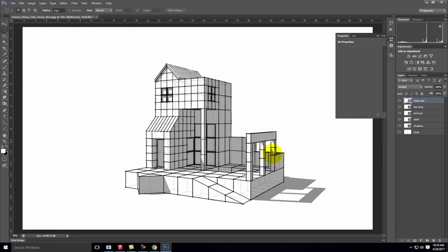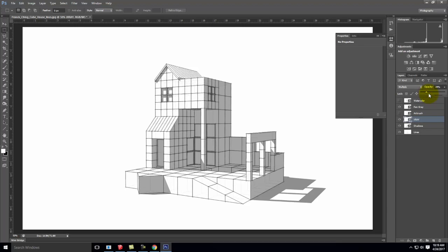So as I layer these up, I'm starting to get more stylistic control that's not limited to just what SketchUp does. The advantage here is I can choose, oh, you know what, that watercolor seems a little heavy-handed. And in this view, my airbrush seems a little heavy-handed. OK, I like this particular view, but my Xray is a little bit strong. I don't want that to be quite so strong. So let's take the Xray layer and change the opacity down to maybe 20%. So it's a little bit there. It gives a little bit more detail, but it's not over the top. You see how that fine control can help what this looks like?